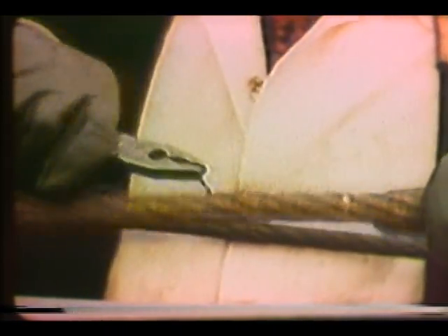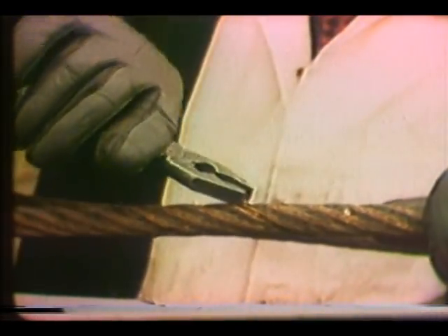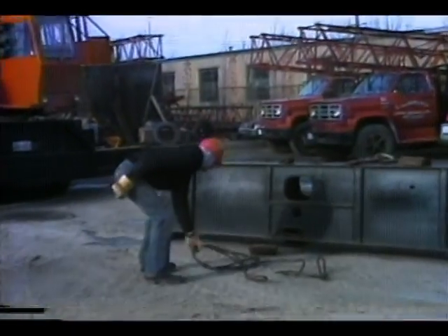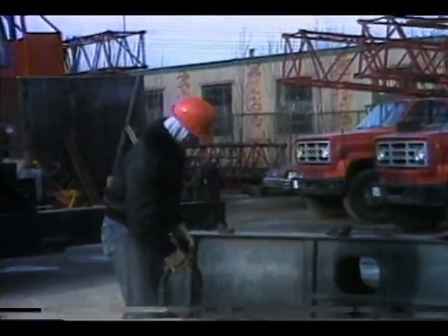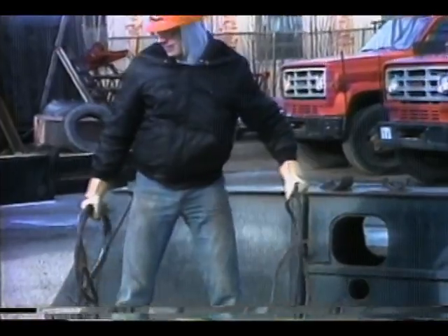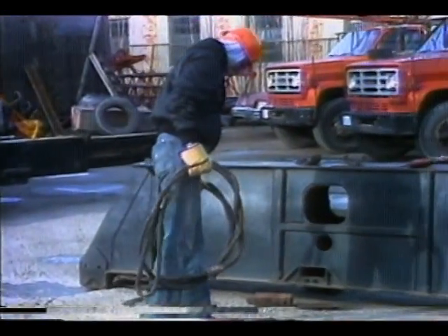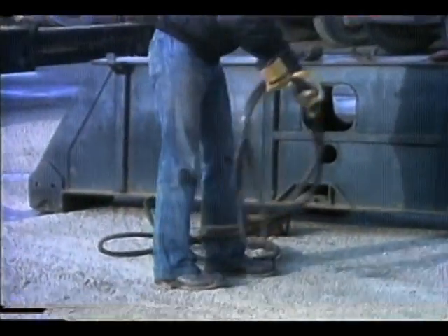Broken wire ends should be removed as soon as possible by bending the broken ends backwards and forwards with a pair of pliers. This way, the wire is more likely to break inside the rope where the end can do no harm. Take special precautions and/or use a larger size rope and appropriate hardware whenever the exact load distribution is not known, there is a possibility of shock loading, or there is a hazard to personnel.